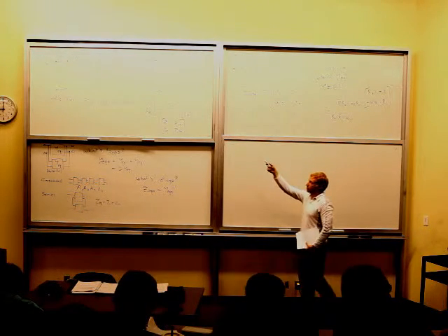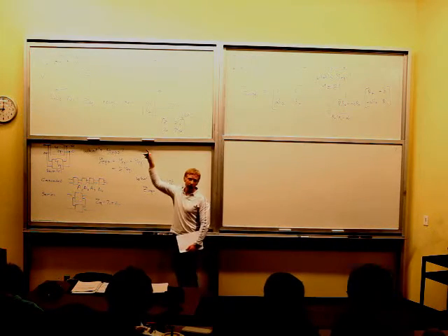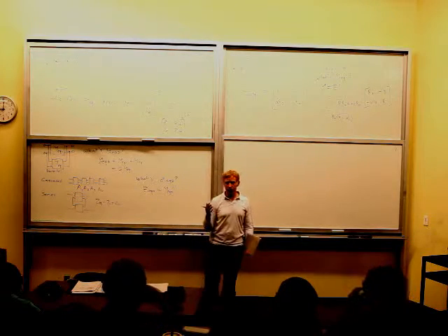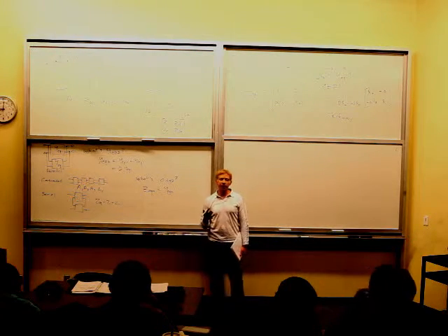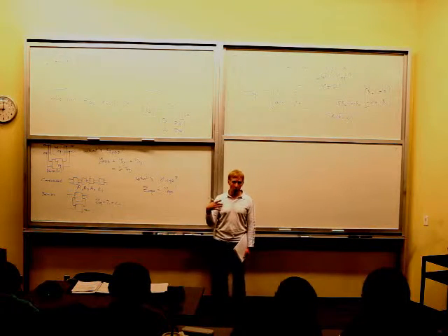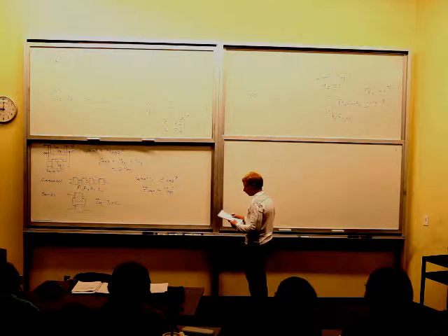The key to solving these circuits, bearing in mind that that was too complicated, is just remembering how you go about shutting off a current and shutting off a voltage so you can analyze the circuit. If you're getting confused, it's always a good idea to draw out the circuit with either shorted or open. That will organize your life and make it a little bit easier.